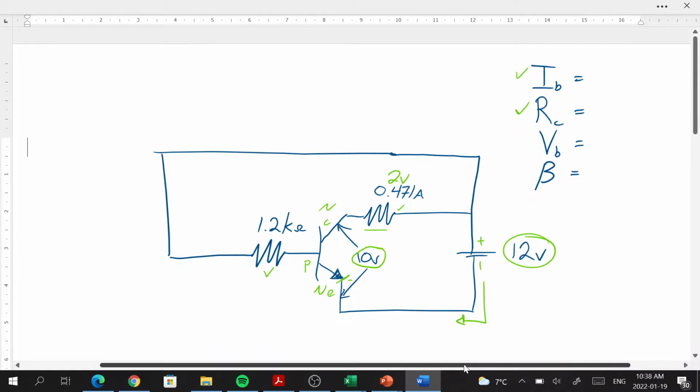Another thing I want you to make sure that you recognize is this. A transistor, between the emitter and the collector, you can think of as a switch. So you'd have the emitter on one side, the collector on the other side, and the switch might be open. Now, if the switch is open and it's connected to, let's say, 12 volts, what potential difference is there going to be between the emitter and the collector? There is going to be 12 volts across it. Because the difference between this side here connected to the 12 volt source and this side here connected to ground, or the other side of the 12 volt source, is going to be a difference of 12 volts. That's what you get across an open switch.